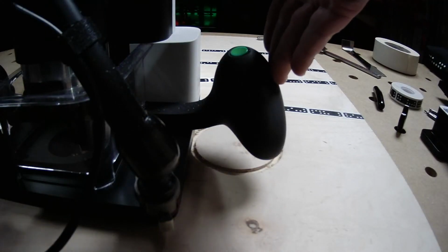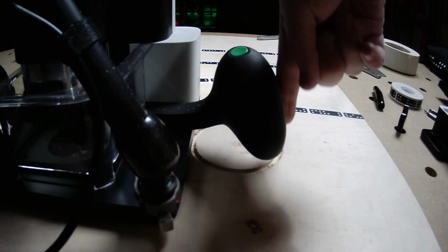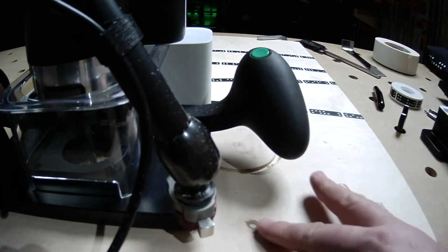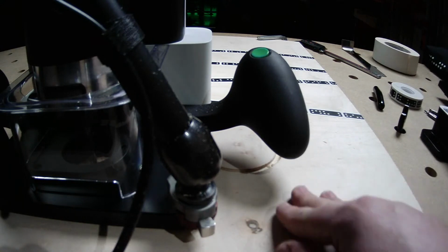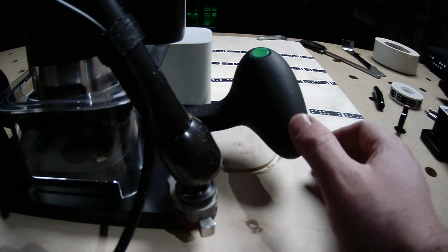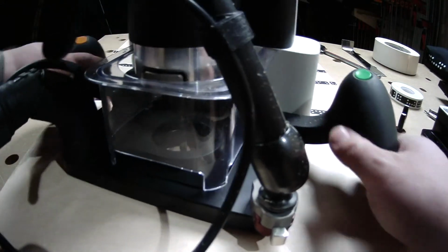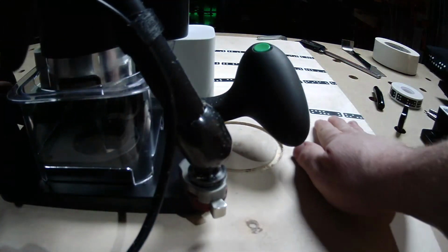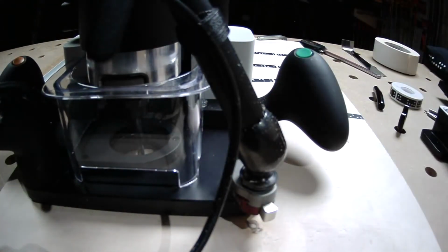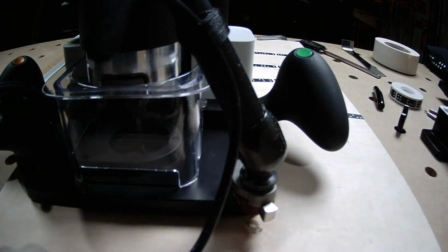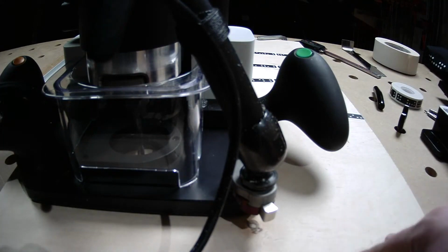Totally. Yeah. So that's the only situation actually where you do want to apply a little bit of pressure to the handle. So if we cut back to the bench, applying pressure down through the handle into the base of Origin is one of the most reliable ways to get a really flat, nice-looking pocket floor. The reason for that is that Origin is riding on the surface of the material here, and if there are little steps or little bumps in the material, you really want to keep a really consistent amount of pressure downwards, and that's going to load the base of Origin such that you get a more consistent pocket.